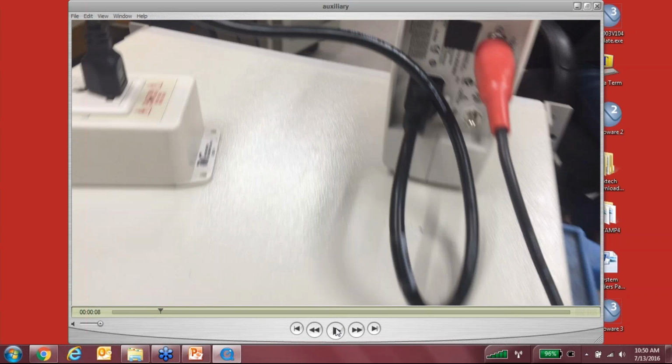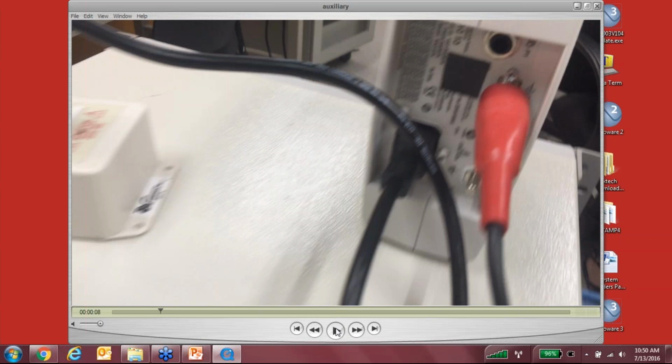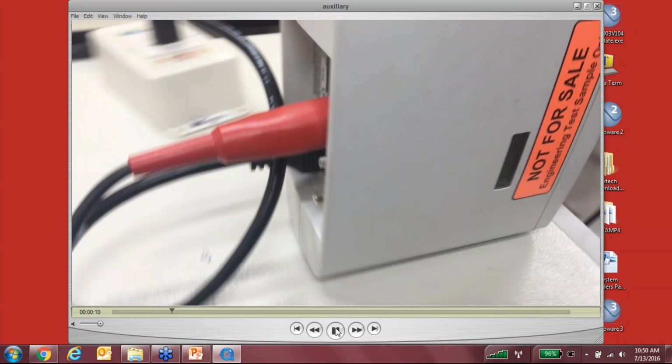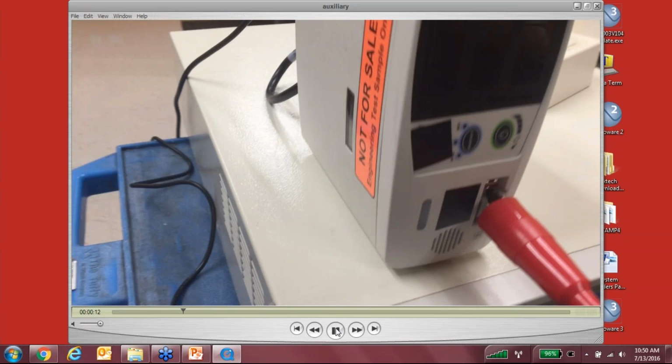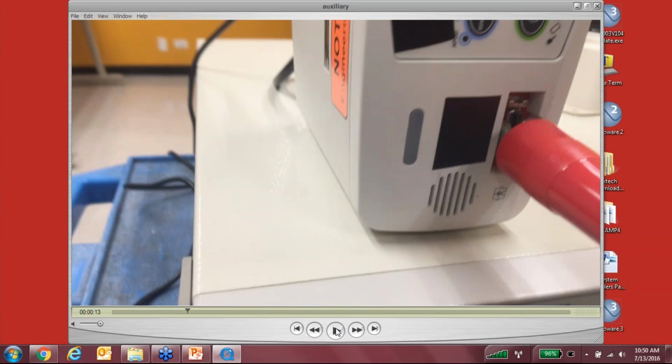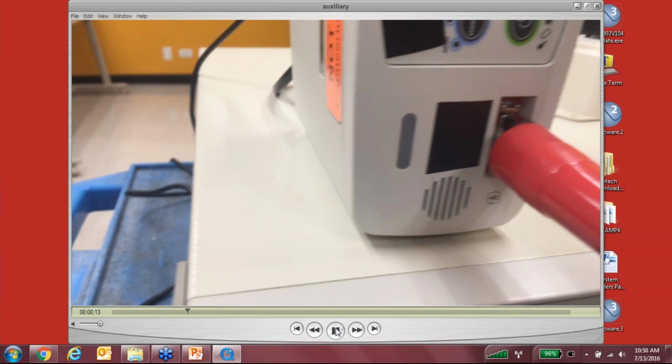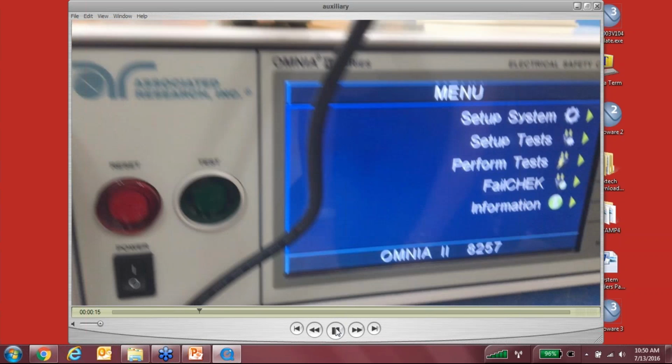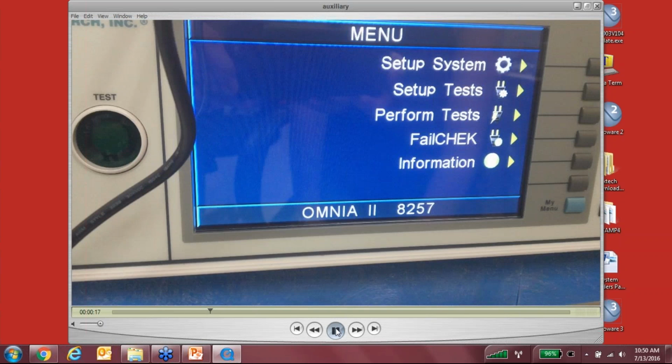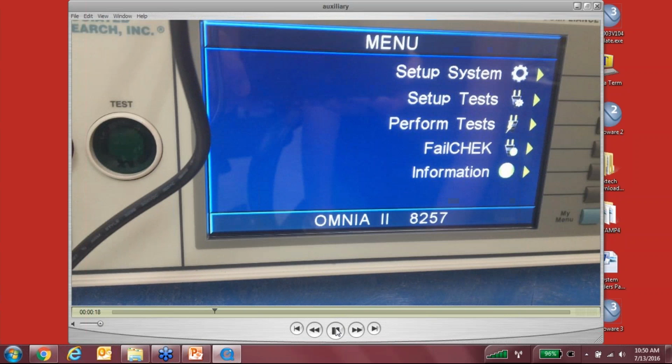So one of my probe highs is on a patient connection on the back, while my probe low is now on that same patient connection I had on the front. So you can see now we're testing on two external points. My measuring device is between these two external points. We'll come back to our tests.